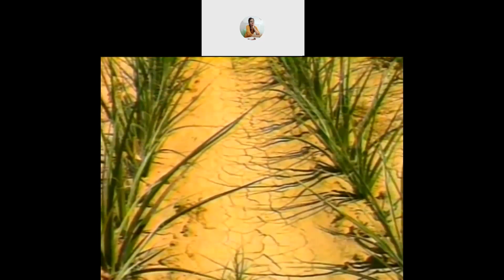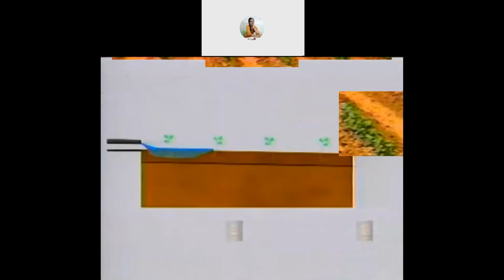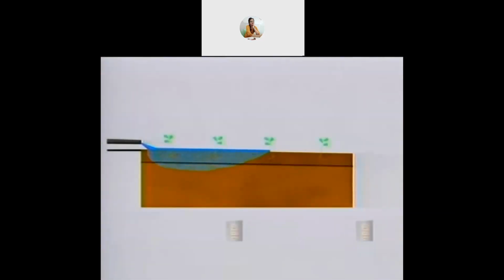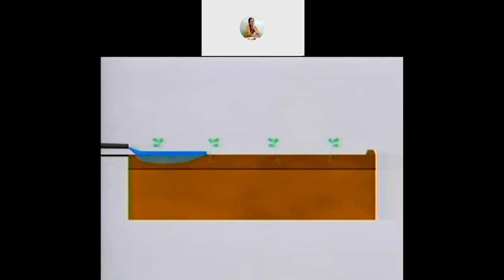The best flow rate and set time depend on the slope and length of the field, the type of soil, the condition of the furrows, and the depth of the root zone. The best flow rate and set time also depend on the type of irrigation: sloped field with open ends, sloped field with the ends closed, modified slope, or a level field.